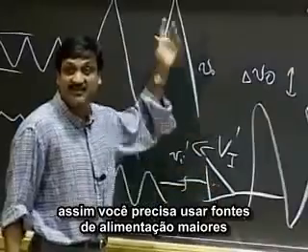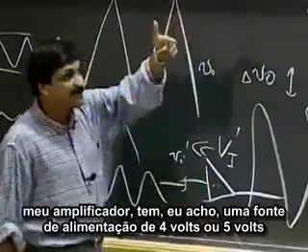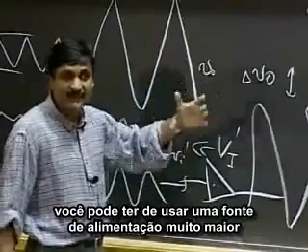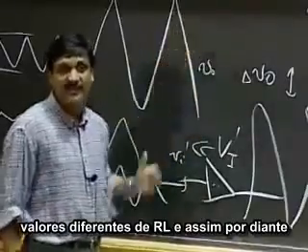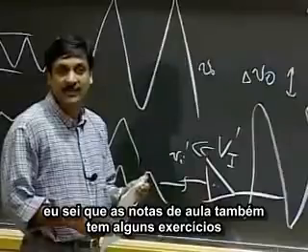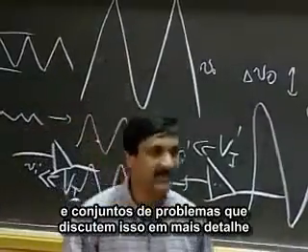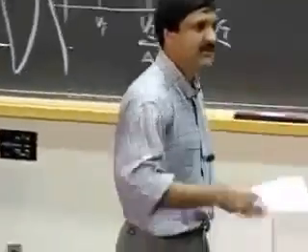So you may have to use much higher supply voltages. My amplifier, I believe, has a 4-volt or 5-volt supply. You may have to use an amplifier with a much bigger supply, different values of RL and so on. I know that the course notes also have some exercises and problem sets that discuss that in more detail.